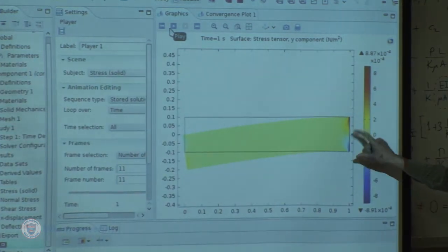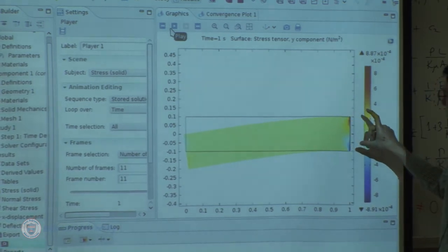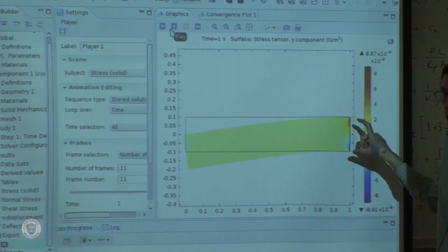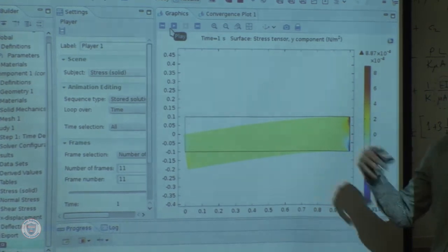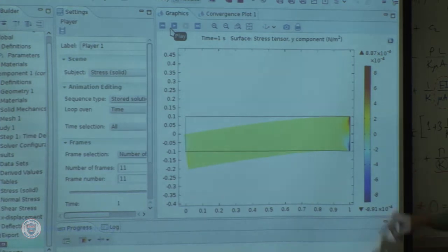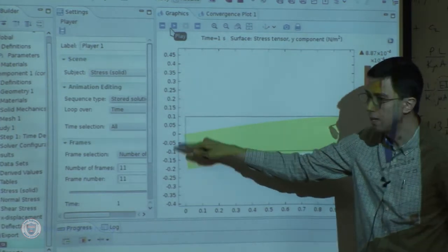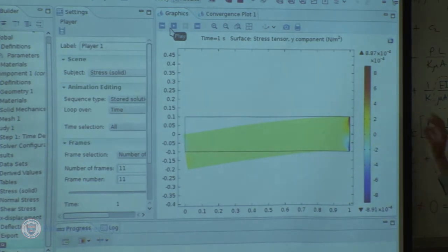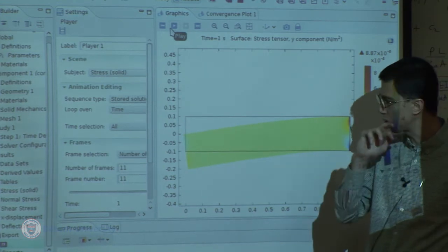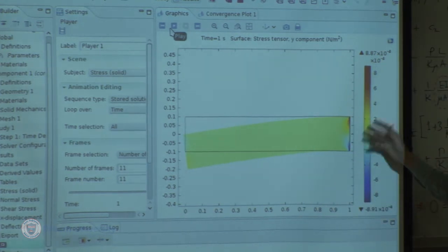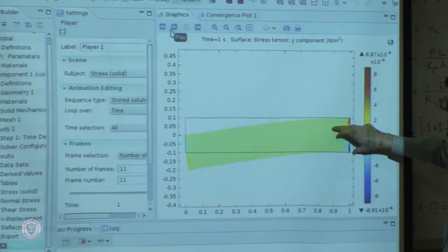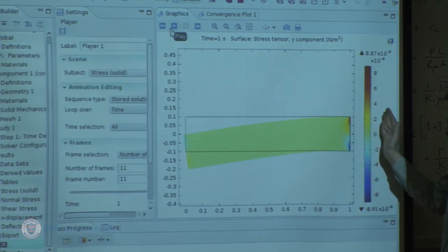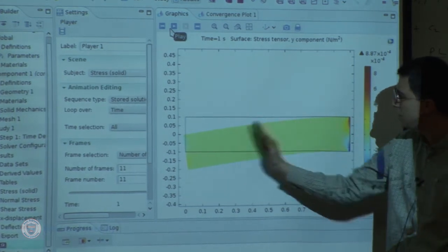What we're looking at here is sigma 2,2, which within our analytical solution, by omitting the end effects, we found to be 0. Now, they are not 0. In fact, they are about one order of magnitude less than sigma 1,1. So it's not really negligible at the ends. But you see that they are limited to a very small region, and end effects always have to do with h. We expect some exponential decay, and they rapidly diminish inside.